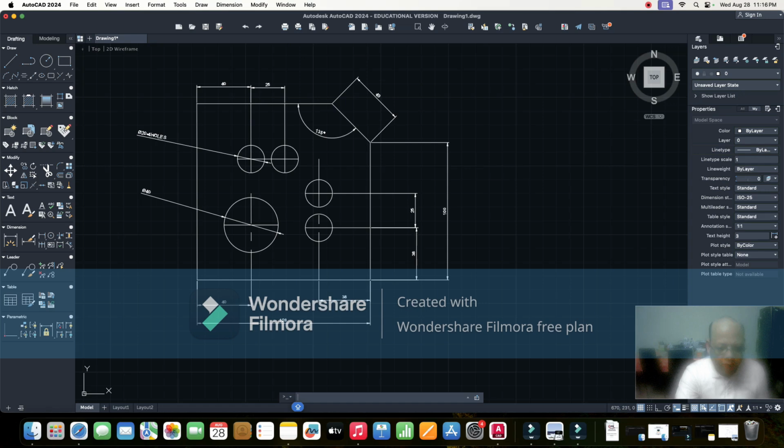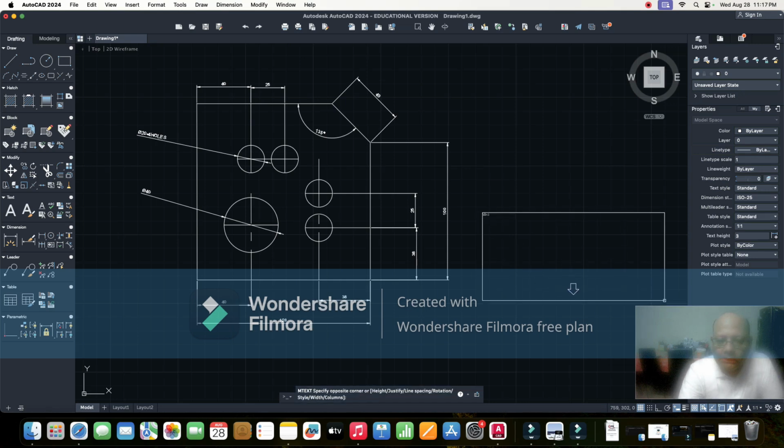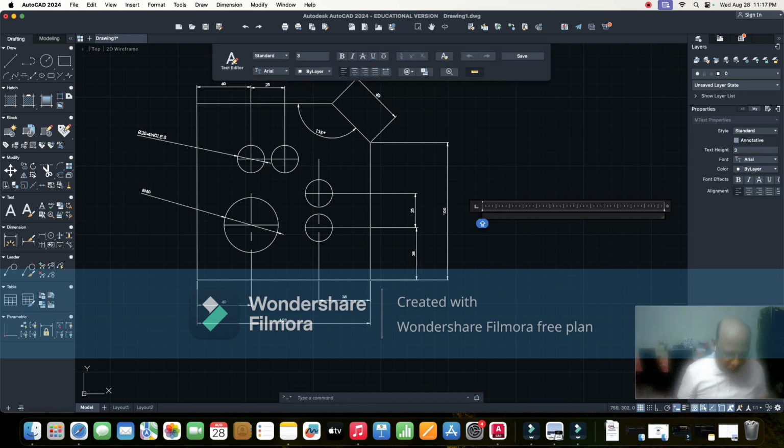So click on M text, multiple text, M text, then enter. After typing M text, specify the first corner point, then the second corner point. Now type your university name, that is Institute of Engineering and Management. You all know this. Newtown.